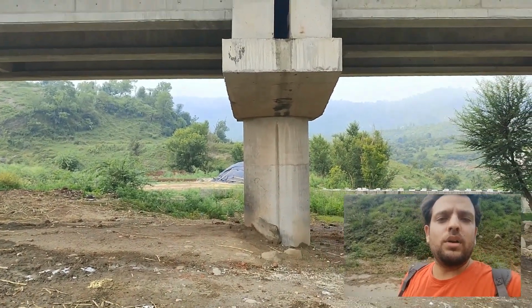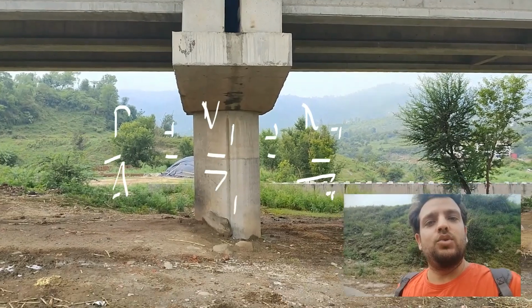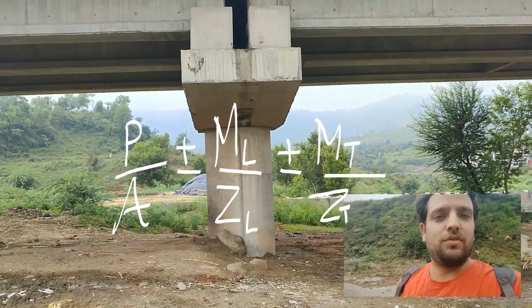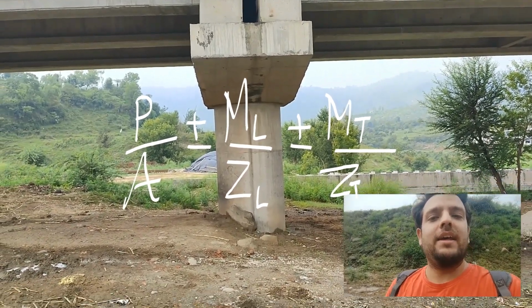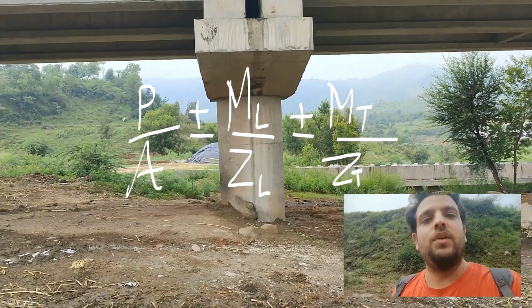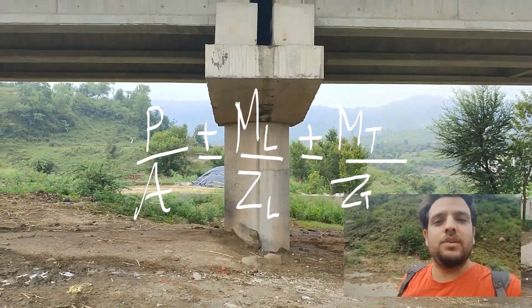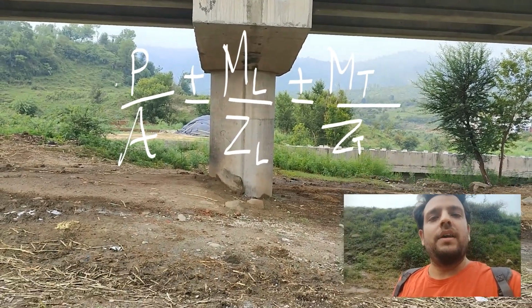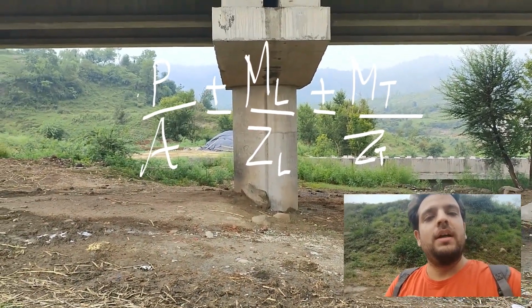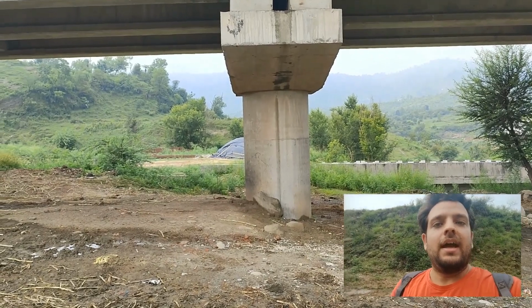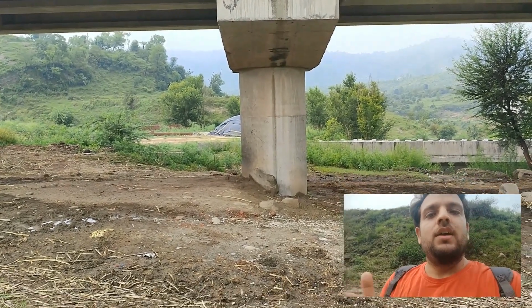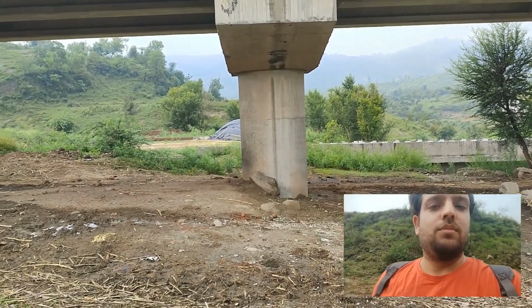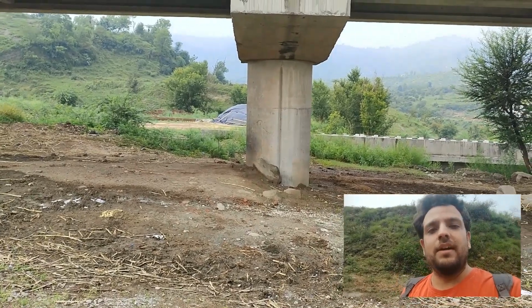So if a longitudinal moment is also added to the already existing vertical force, you will notice that one tip of the base pressure diagram will be more stressed, simply by using the concept of M upon section modulus, and hence a uniformly varying load is subjected to this footing. For designing the footing, the section which needs to be designed for the moment has to be very well identified.